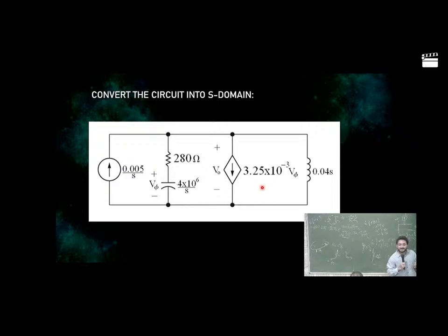But I wanted to know, sir, how it is actually realised in the circuit. That's what we plan to do, but we will implement it using a BJT. We don't have a voltage dependent current source available in the market. We have voltage sources that supply voltage, but we don't have dependent sources available in the market. So for making that we use a BJT, a bipolar junction transistor.